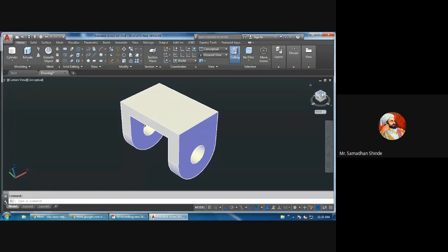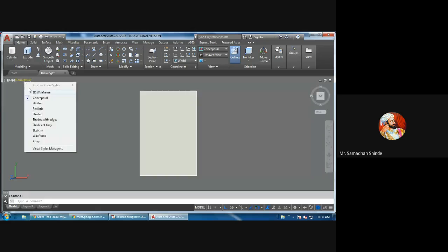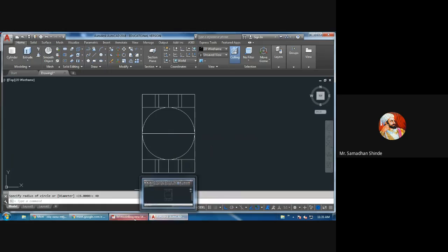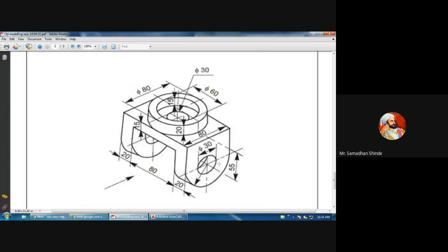So this top plane. What do we have to do? Here we have to draw one circle. Okay. Before that, I will draw a line, this to this. Here there is a circle of how much? 40 radius, 40. Then all the circles we will draw here. Then how much is the inside circle? Whatever throughout circle is there, throughout it is 30 diameter. Throughout it the circular hole is 30.